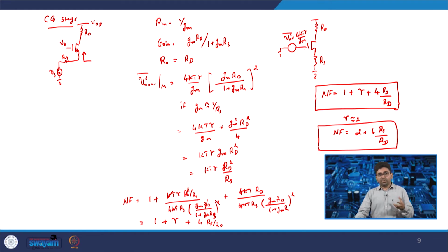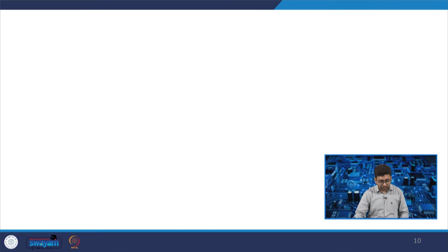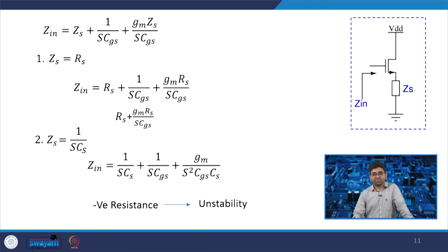So now how can we reduce the noise figure? This is a question. In order to reduce the noise figure, we need to get the input impedance of 50 ohm, that is resistive, without using a resistor. Can we do that? Without using a resistor, can we get an input impedance of our desired value? Let us try one topology. In this case, you just stay with me.